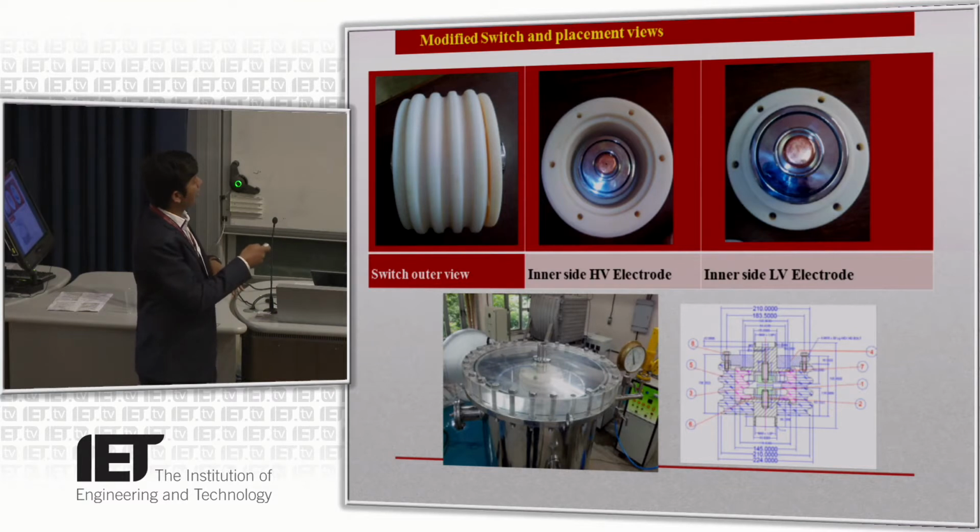Now in that system, initially the peaking stage is not at a different pressure, because the capacitor and peaking stage are at the same pressure. That's why this peaking stage needed to be modified. This is the newly modified peaking switch, which is placed inside the Marx tank at the top of the tank, and this arm is coming out. This arm is fed to the launcher or feed arm of the reflector. There is different pressure in between them, and this is the AutoCAD drawing of this switch.